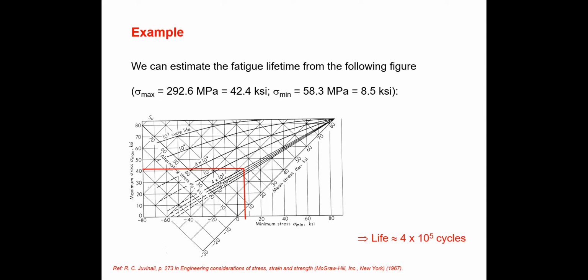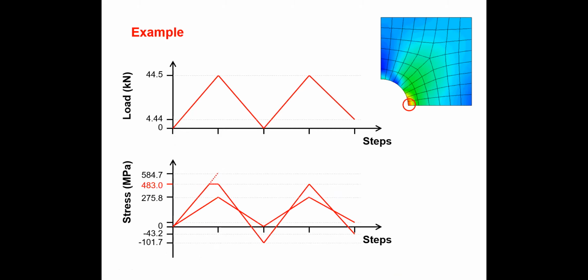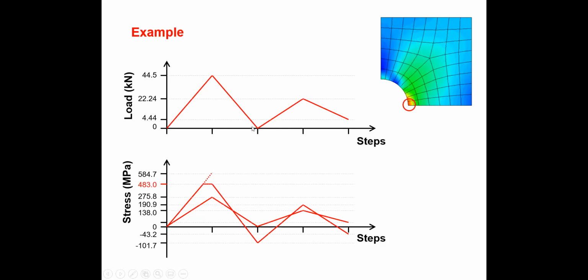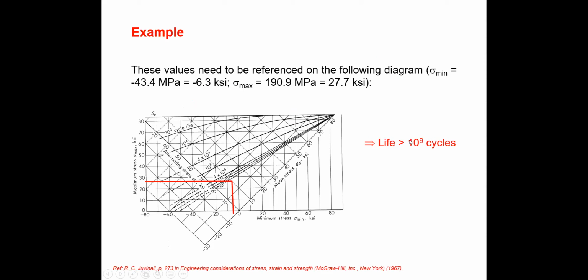So what are the benefits? You asked what is the import. So what is the usage of this one? Usage is you can apply this one for the element, the component. If it is a shaft, to increase the lifetime of the shaft with the loading pattern. So you can see in here, same loading pattern without preload, it is 4 times 10 to the 5 cycles. But if you apply preload, only one cycle preload with higher load, the material will be warmed up, then lifetime will be increased.